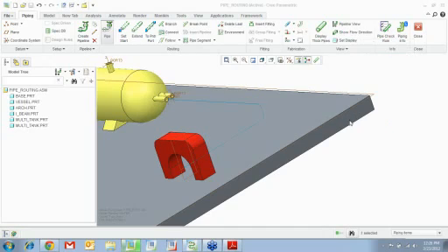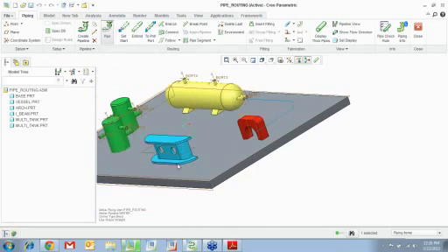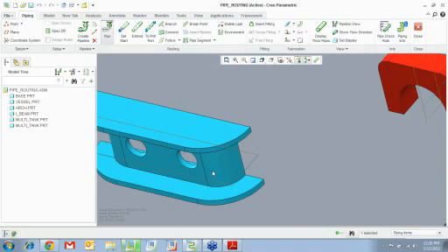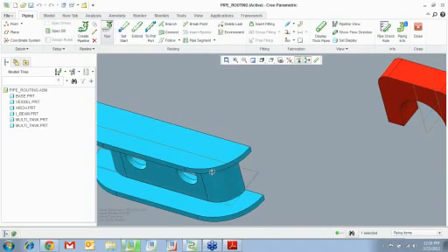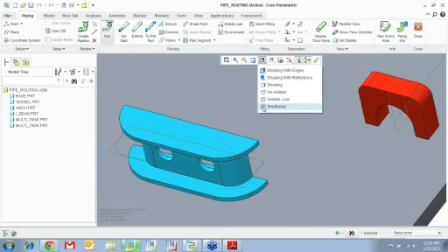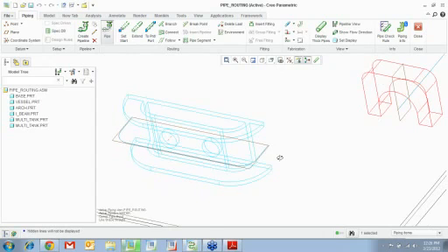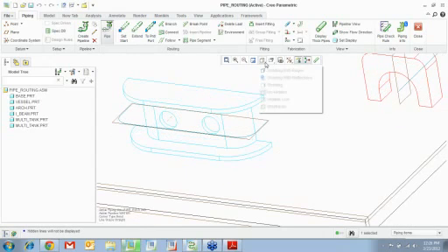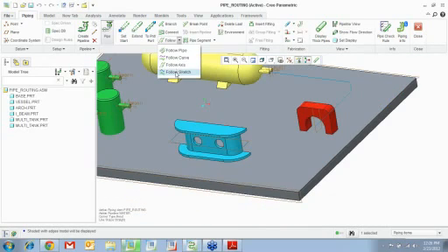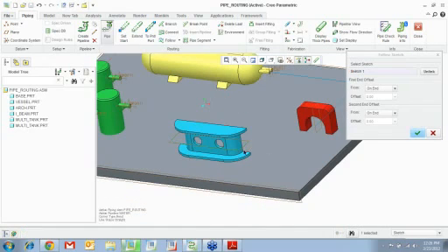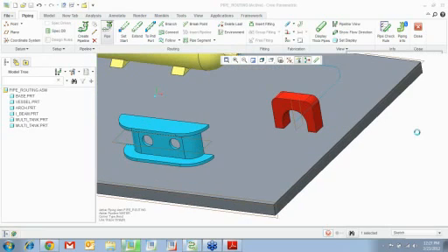Alright. So now that you've connected that, I want you to also see that there is a little sketch over here. Fortunately, that part's in blue color. It's very bad of me to do that, but you can look. You can see there is a sketch on that particular plane that I'm going to use to follow. So I can say follow a sketch. I'm going to pick that sketch. I want to go from the start of the sketch to the end of the sketch and say OK.